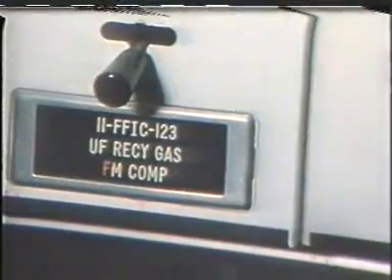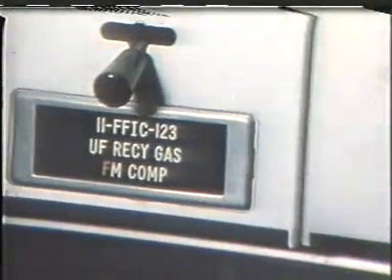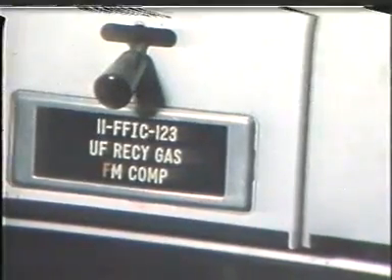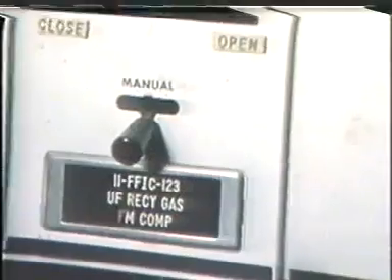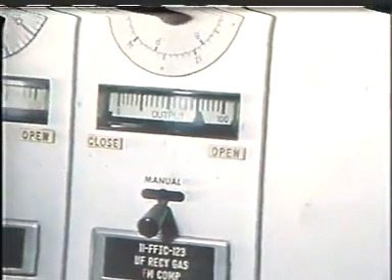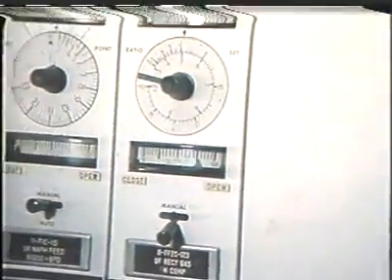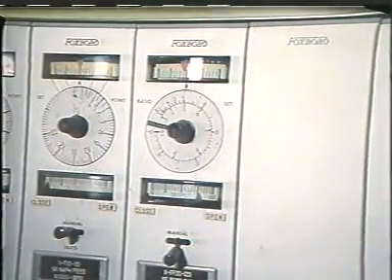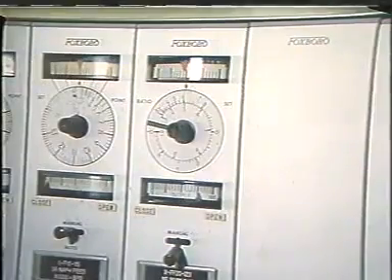If the hydrogen recycle ratio is not kept above a minimum value, coke deposits may force an early shutdown for catalyst regeneration. There are several situations, such as a lower concentration of hydrogen in the recycle gas or a reduced compressor capacity, that can cause the hydrogen recycle ratio to decline.